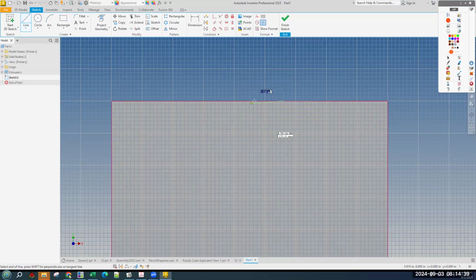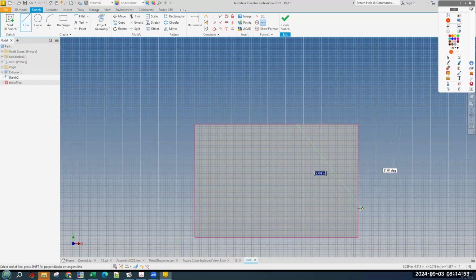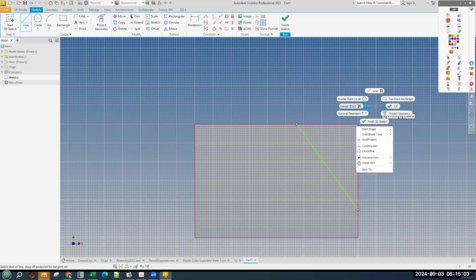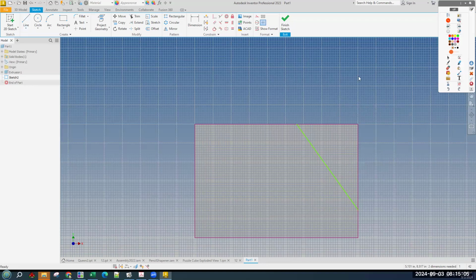Okay, a lot of times snapping to the middle is useful, but in this case it's not. If we put it there, it wouldn't let us change it. So our first click is on the top line, and our second click is the same. It's somewhere on the sideline, but not the exact middle point and not the corner, just somewhere on there. Okay, and we can do right click, cancel, or the escape key on the keyboard to get rid of the tool.